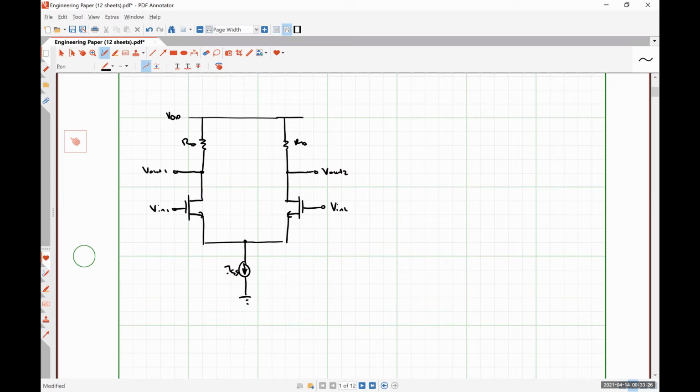All right, so let's briefly discuss how we can make this have a single-ended output. We just take the output at one of them. That's it. The problem with that is that we're only going to see half of our voltage gain, okay? So if we don't take the difference of those two guys, we're going to have some DC shift to our output, and we're going to see that it's amplified only by a factor of 1/2 because we are not getting the full amplification of our differential input signal. We're only looking at the variation on one side of our half circuit, not both sides.